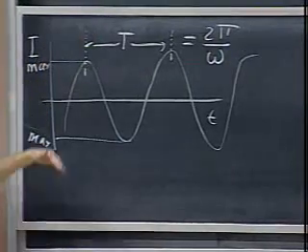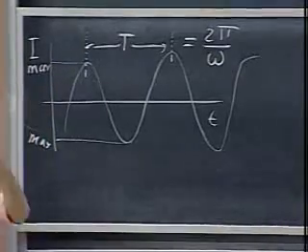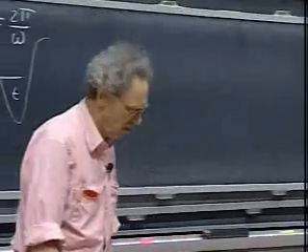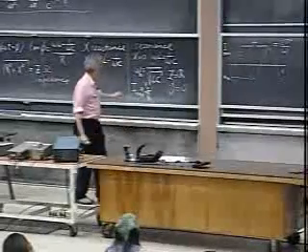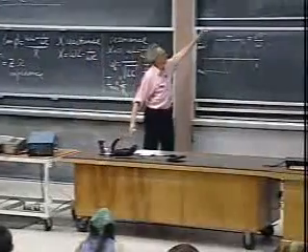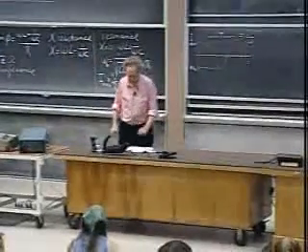If Z is very high, this will be low, and there is only one value of Z for which the system is at resonance, and that is when the self-inductance and the capacitor eat each other up, and then you get the maximum possible value for the current at maximum, which is V0 over R. And that's the highest value that you could ever get.